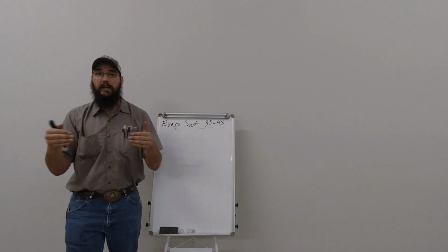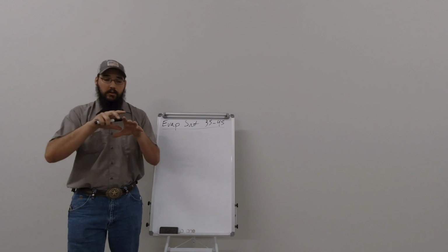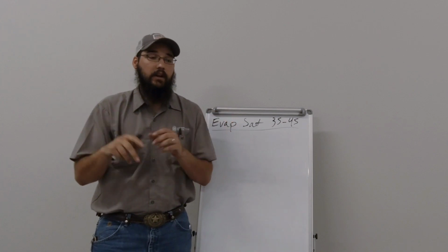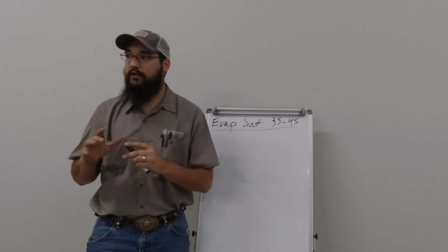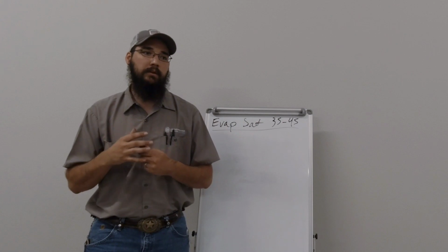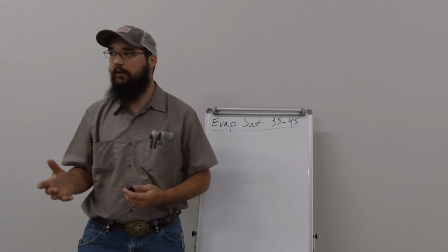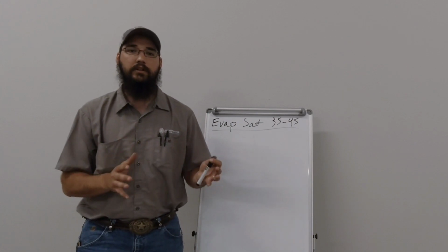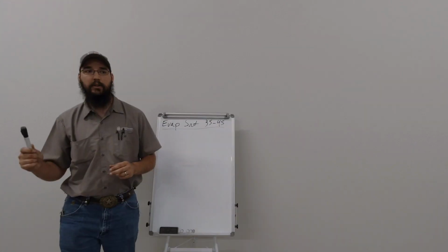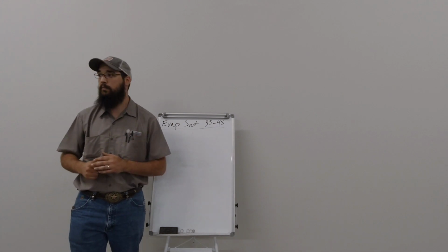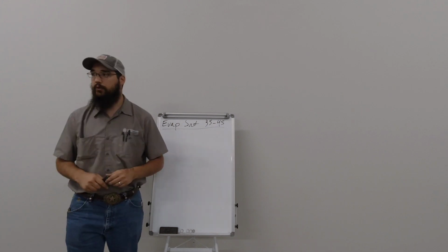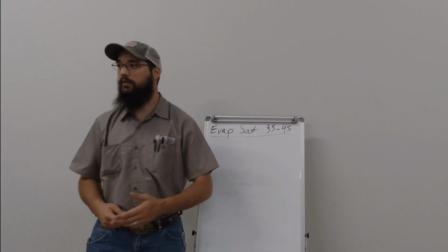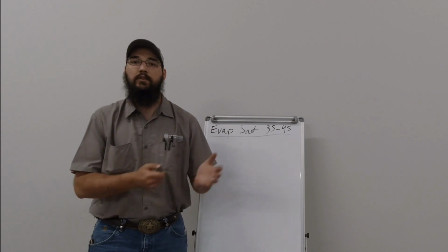That's just how critical those saturations are, because everybody gets hung up on pressures, especially old school techs. I love them to death. I was there at one point myself, but pressures in my book are only a means to an end. That's all the pressure is. What's most important has nothing to do with the pressure, it's the saturation itself. Pressure is just there to tell you what your saturation temperatures are. Once you know what those temps are, you dive in deeper from there. Doesn't matter if it's 410A, R22, 407. The pressure is just a means to an end.